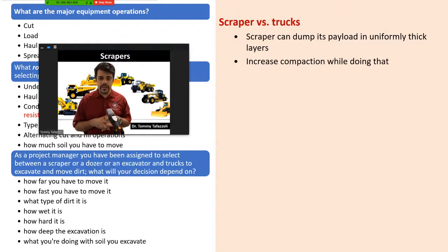It increases compaction, right? Because the load of the scraper itself will be exerted on the road surface, and that will contribute to the compaction of the soil. In good compaction, uniformity of the soil goes a very long way. It's very important. And using the scrapers, you have a free mind. You know that you will get a pretty good spread for your dirt.